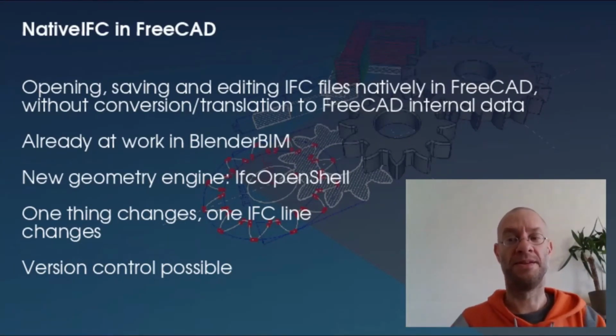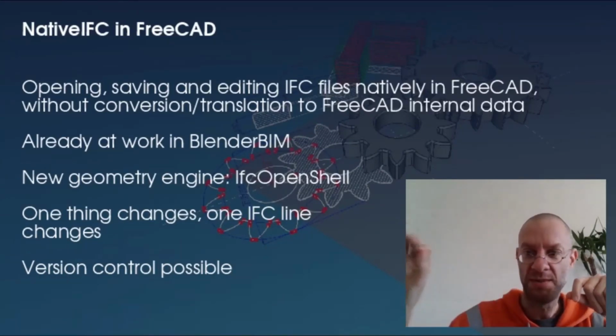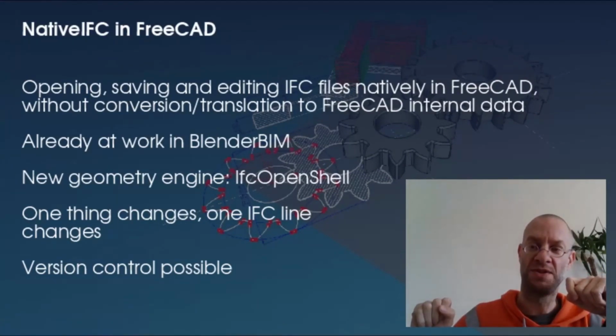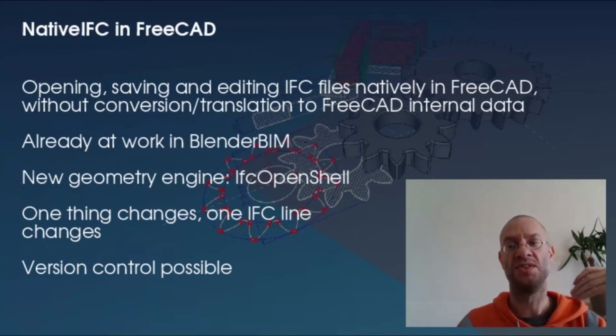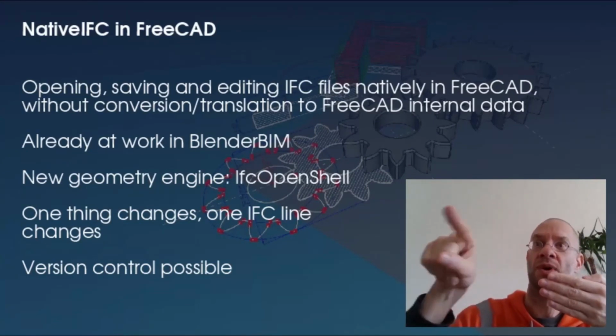And there are very interesting consequences to this. If you change one thing, the name of an object in FreeCAD, there is one place in the IFC file where it has changed. So this makes it very, very friendly to version control. A version control system can give you two versions of an IFC file and show you where things have changed.